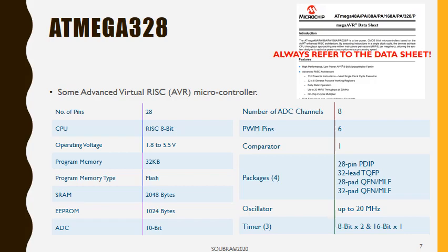Question in the back. Yeah. So I'm telling you that the operating voltage of my microcontroller, so my microcontroller, is it the whole board? No, it's just that component that we've seen on the board. It could be one component on the board. I'm telling you that the operating voltage is between 1.8 and 5.5 volts. My question to you is, if I apply 10 volts to my microcontroller, what would happen to it? Barbecue. Should I ever apply high voltage to my microcontroller? Never. Fair enough.